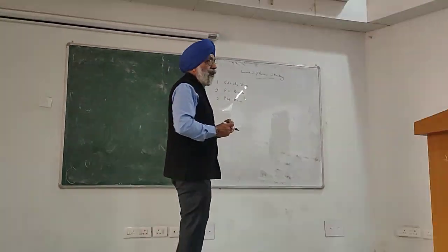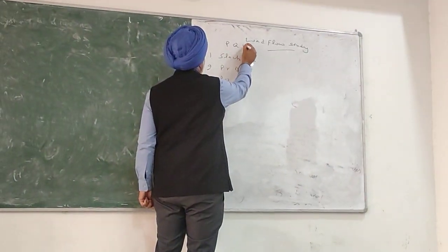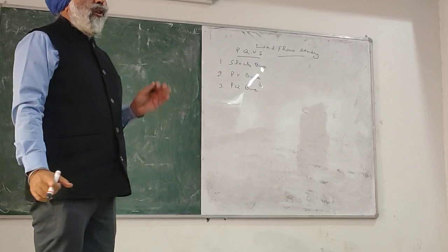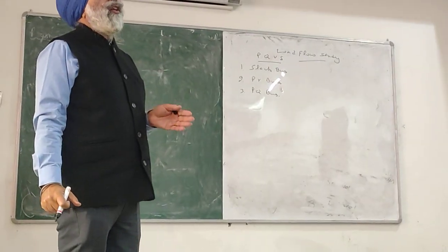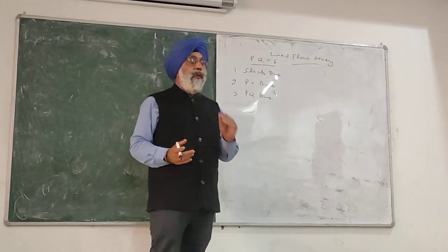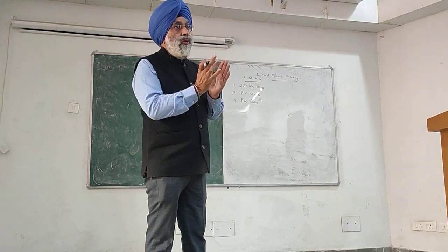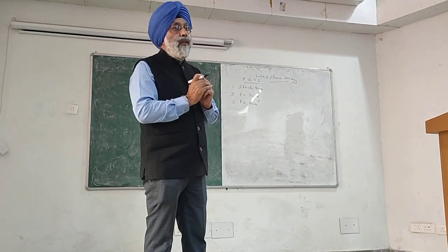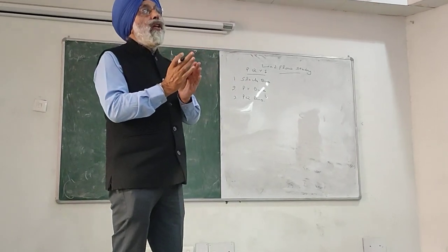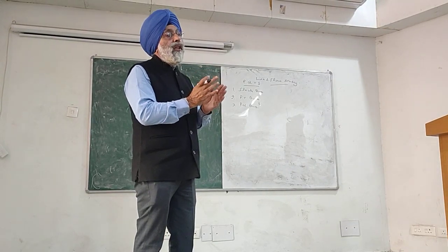All the buses are the same, and at all the buses we have four different quantities: P, Q, V and delta. At all the buses, P is the real power, Q is the reactive power, V is the voltage and delta is the angle of the voltage. Out of these four, we provide the control at a bus so that two can be kept fixed at that bus, and the other two become variable. Means they have different values according to the fixed value of the two.